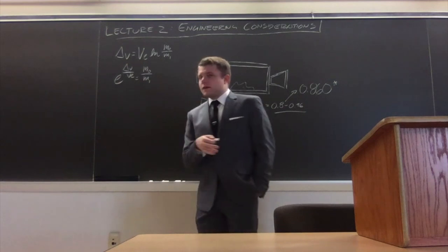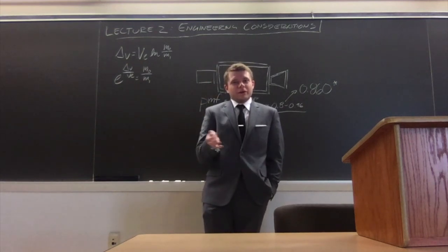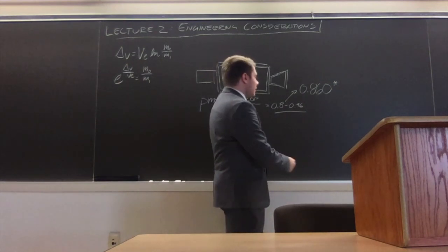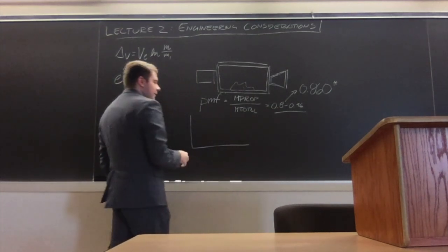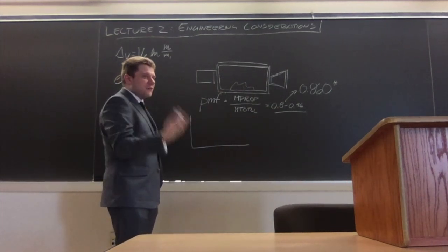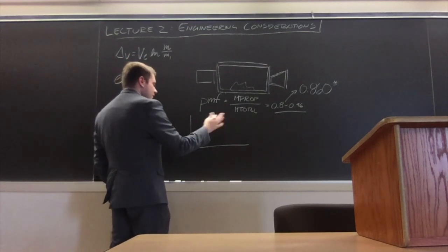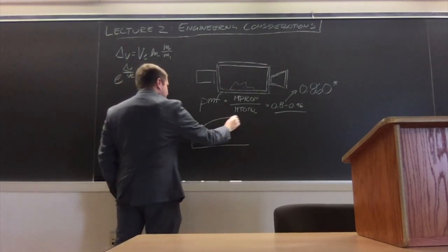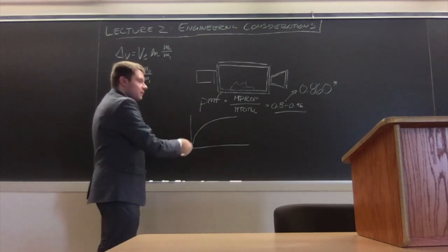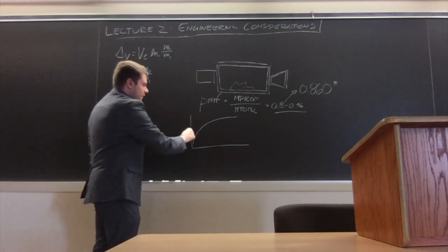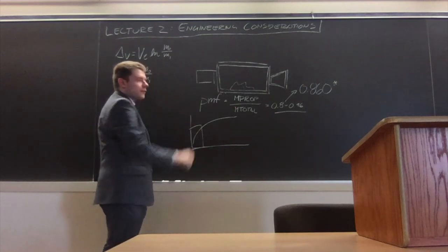So the problem is that it's not really a linear scaling when you're dealing with a pressure vessel. You think about it like this. The size of your pressure vessel generally means a much heavier one for a much smaller volume, so your efficiency looks something like this. It kind of behaves linearly when you're dealing with very large volumes, but not so much when you're playing with the small stuff, and we're kind of playing with the small stuff.